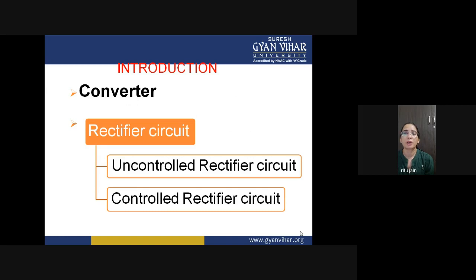And now it will depend upon you whether and when you want to apply gate current across the SCR. When you apply only voltage across the anode and cathode terminal of the SCR, the anode terminal will be positive and the cathode terminal will be negative, but there is no gate pulse, so the SCR will not be in conduction mode.